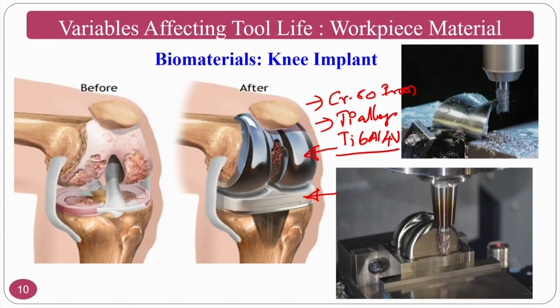For that purpose there are post processings, not only the milling, but the basic process has to make sure that it is in good shape with good surface roughness. If you are machining, you have to use advanced tools, and at the same time take care that the tool wear is as minimal as possible, so that you get proper roughness and proper metallurgy on the workpiece.